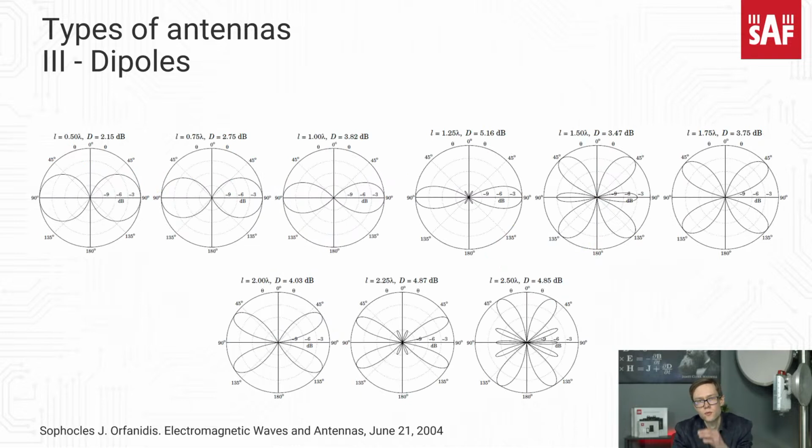And this is how we can find different radiation patterns in the elevation plane. Let's imagine this is the side view of the transmitting element. This is what we get if we change the dimensions of this antenna. Let the frequency be the same for all of these pictures. So we assume this antenna is used for a constant selected frequency, but we change the dimensions, starting from half a wavelength on the very left of this picture.